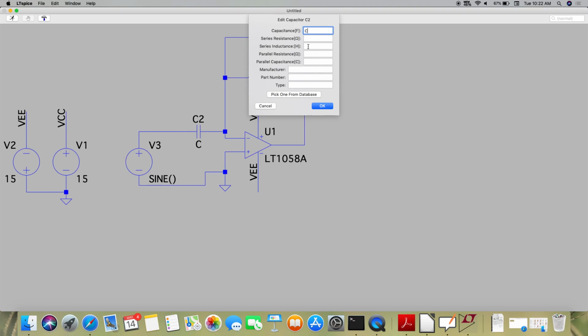So what do you think could be the reason for adding these things also? These are the parasitics, right? In reality, resistance is not pure resistance, capacitor is not pure capacitor, or inductor is not pure inductor. You'll find some more things. And if you want to make something very specific to some manufacturer, you just add that manufacturer and find out these values. These values will be available in the data sheet of the particular resistor or capacitor. You need to find it on Google. It's available very easily. The first search will give these values, and you add them here to make everything like the real scenario.